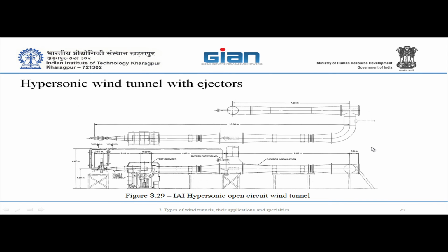Originally we had three nozzles for Mach 8, 10, and 12, but over time they added Mach 5 and Mach 6. A cooling system is also incorporated on the nozzles. Why do you need a cooling system? Because of the high temperature flow, you have to avoid liquefaction. You will be heating the system. Cooling is there for the nozzle, and sometimes you want to cool the model, but mostly the nozzle is cooled.